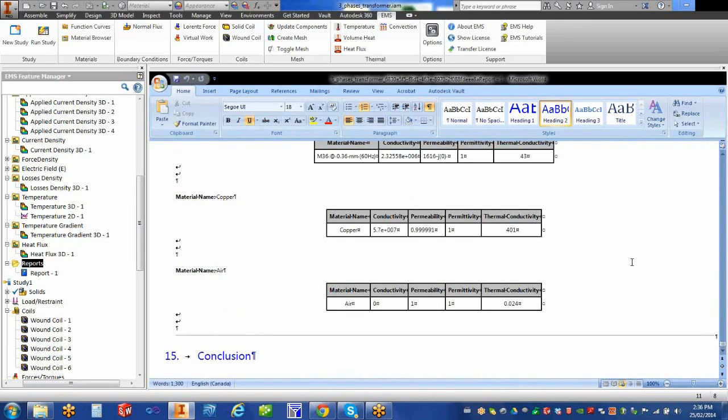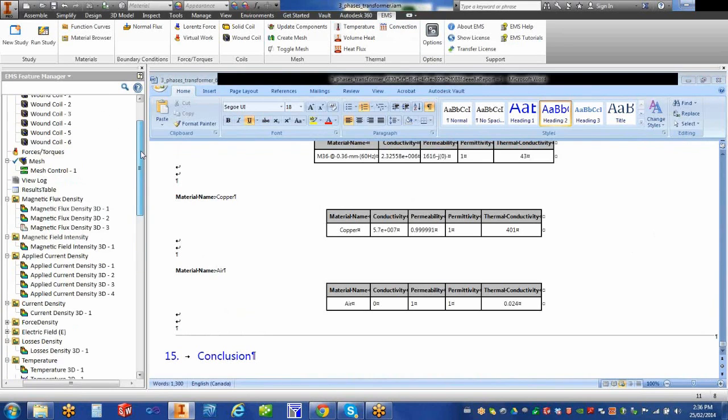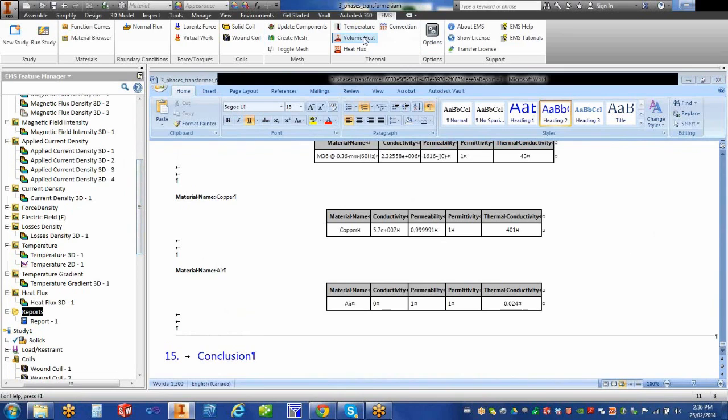So, okay, to sum up, in EMS, in Inventor, you can do either just a simple electrical simulation or electrothermal, or you can even just do a thermal application, by the way, because if I apply zero current, I can apply volume heat, which I can use to do a thermal problem without the electric part of it.